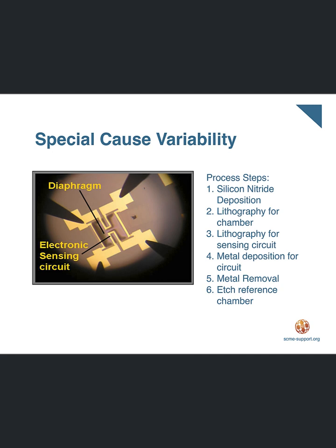If one or both of these variables change during the coat process for a batch of wafers, then the final thickness of the photoresist will change from one wafer to another. Small changes in these variables are acceptable as inherent variation of the process. Any change outside of this inherent variation is unacceptable, and the cause must be determined and corrected.